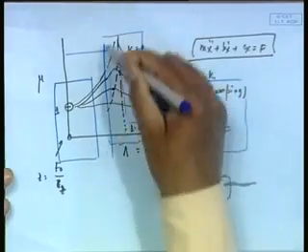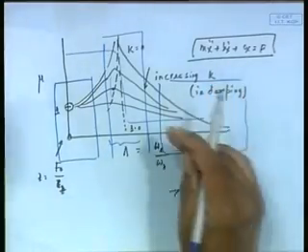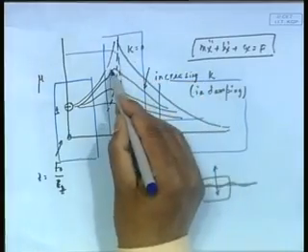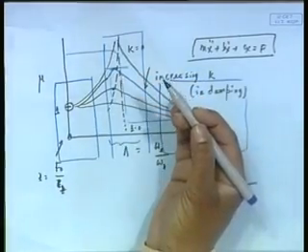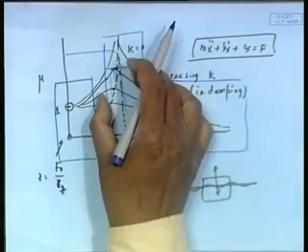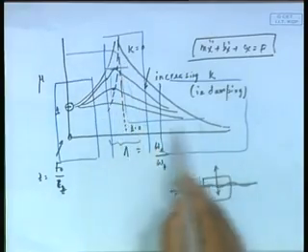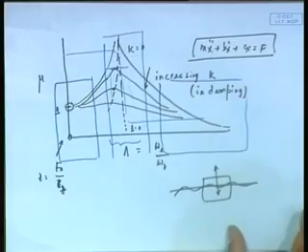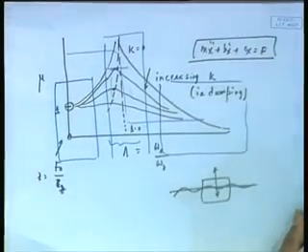So, this inside part, we can call damping dominated motion, but it is a very small part only, because really speaking, estimating this amplitude requires a very good estimate of damping B, and damping is always very difficult to estimate, but we can call it damping dominated. And in fact, theoretically this is where there is a change of phase of that Ez value. Ez actually undergoes a phase change in this case. So, this is the kind of modes of motion that we find.